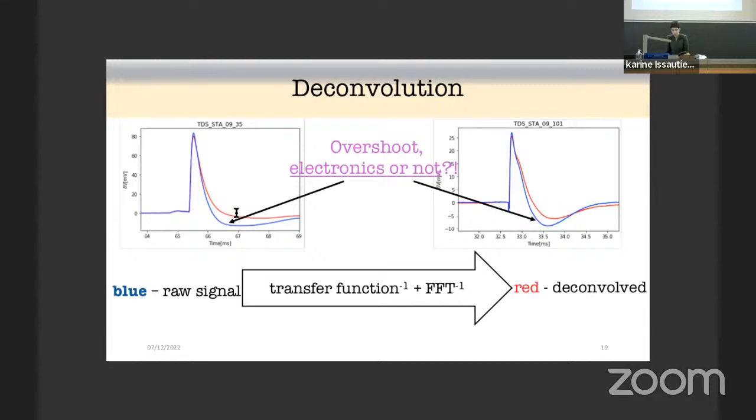This is that, okay, for the signal, we expected to see the beautiful one that we actually present with our mathematical equation, but it was not really like that in reality. Which is okay, because we are measuring the difference between the voltage of the spacecraft and of the antenna, the difference in voltage between 2 spots, but between those 2 spots there is a chain of electric things, so it's to be expected that they will somehow affect the signal.